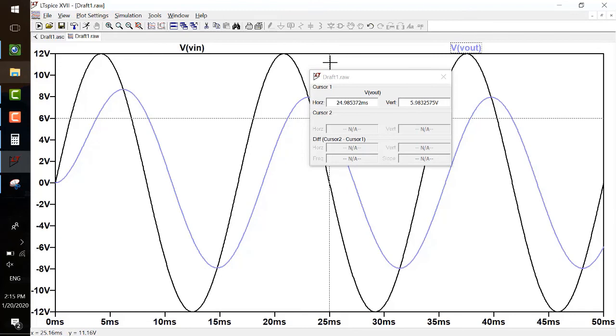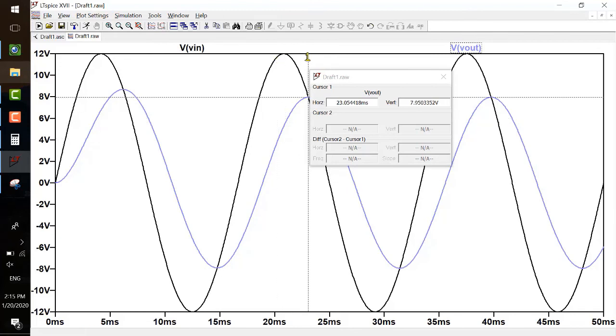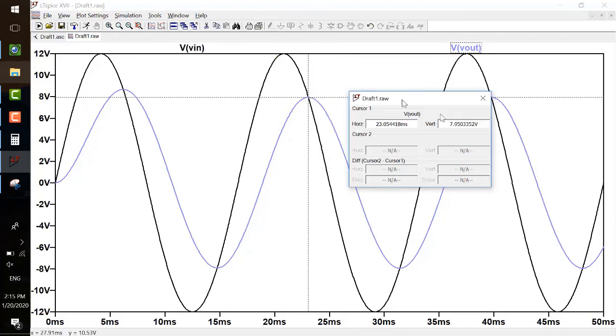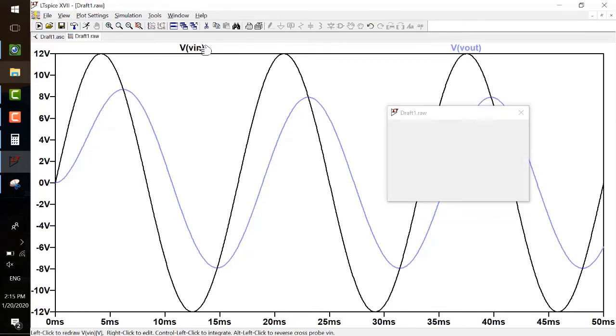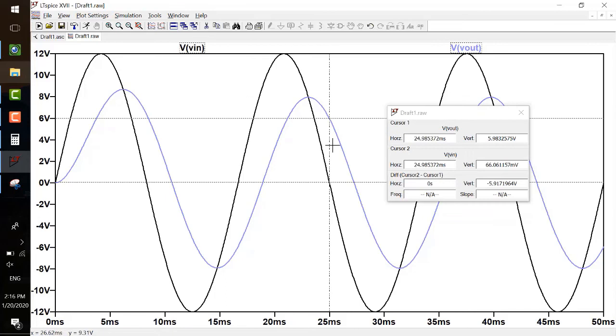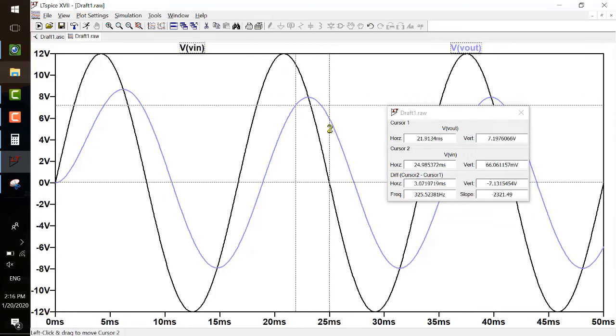If you know how to bring up two cursors following two different signals, let me know. Sometimes I can accidentally do that. I did that a few years ago. I forgot. So see that control. You just double click on one of them and then click on the other. Okay. Boom. All right. So this guy is following V out. This one is following V in.